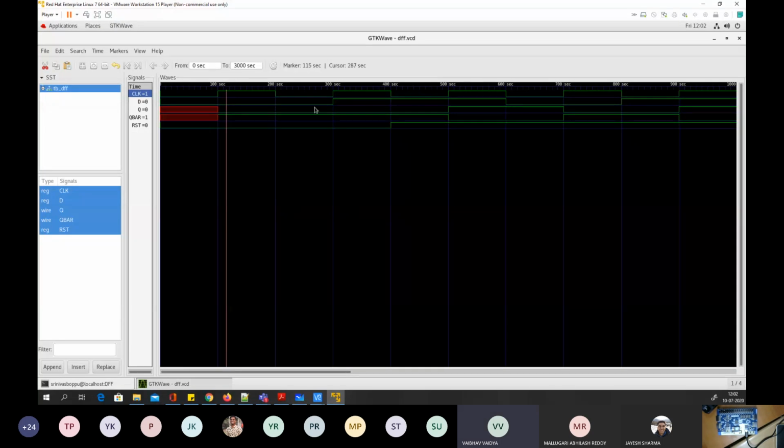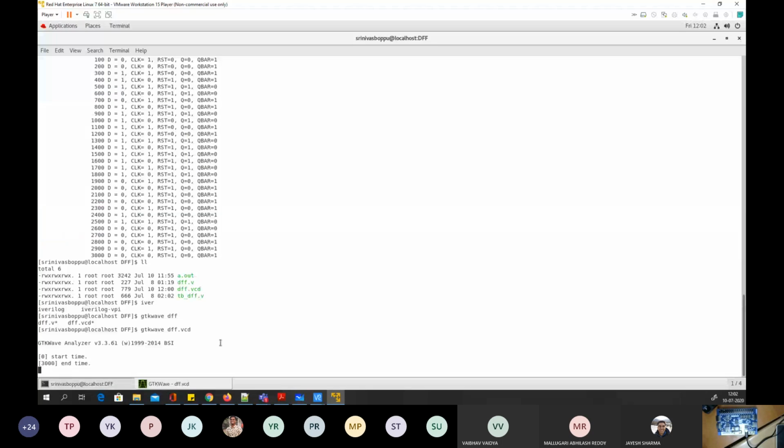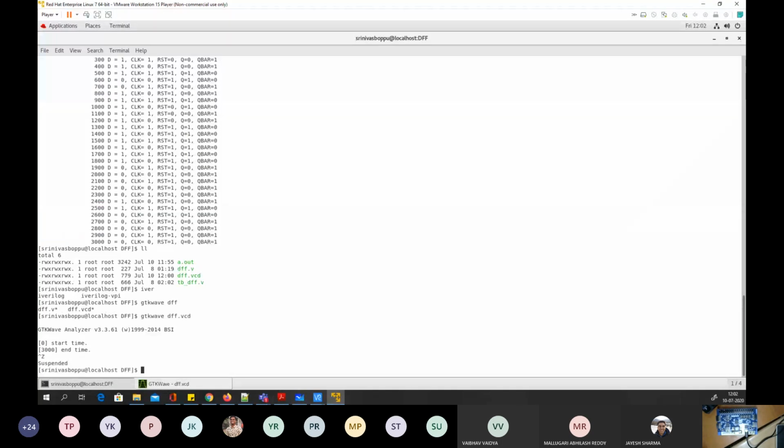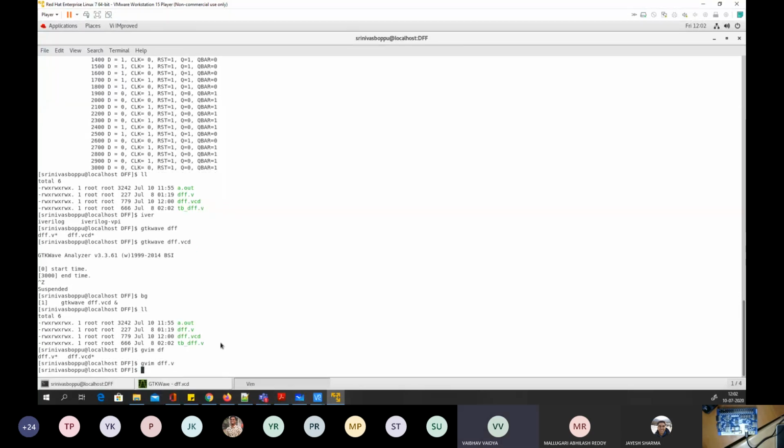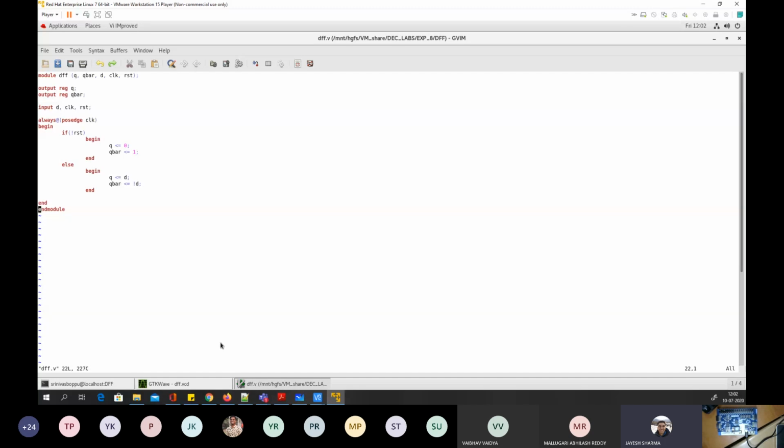Yes, sir. Okay, now let's look at only the reset input first. According to our logic, is it active high reset or active low reset? Active low. How many agree with Vaibhav? Yes, sir, low logic, low reset. If you see here, if reset equals 0, this is getting active, so this is an active low reset.